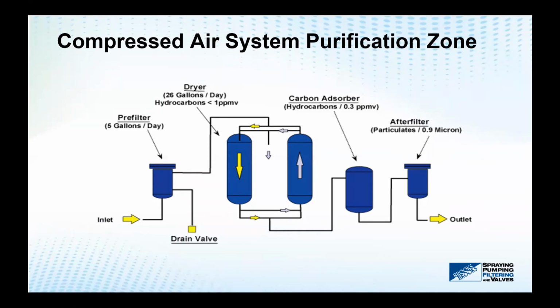I agree. And apart from just going right through the dryer, if it's a desiccant dryer, it can also destroy the desiccant to a certain extent. If you have oils in your liquids, then that can destroy the desiccant. And I always like to bring up one of the most important components I find on the compressed air purification system, this very economical drain valve. If this fails, then you can have liquid oils, and as you previously stated, the desiccant dryer is not made to remove liquids. So this would overload the dryer from a liquid standpoint.